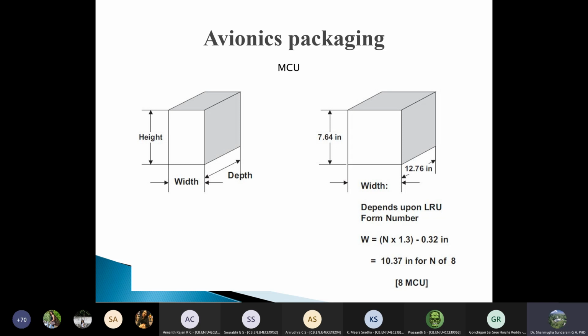So examples include interfacing multiple avionics systems to achieve a common functionality. Okay, examples are the inertial reference system and the air data computer. Together they constitute what is called an air data inertial reference system, and it has advantages because a unified representation of the aircraft attitude parameters as well as the navigational parameters can be obtained out of this.